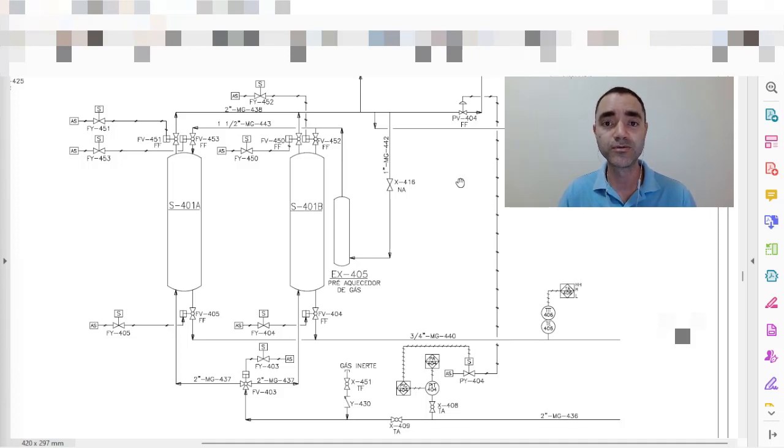But the plant does not run only at the design case, because it depends on a lot of circumstances: the market, whether we need turndown or not, how many machines are available. So most often, besides the design point, you need to consider what is the minimum flow required to have the production of your process. The lower you can go in production without stopping the plant, the better.